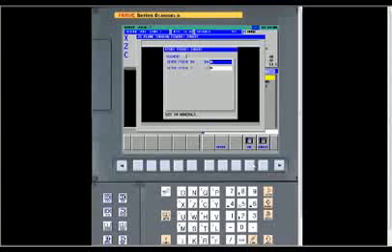You don't have to allow for out in front of the part, because that's within the cycle where we told it to start 100 thousandths away. So it's important when you do this geometry, the trouble most people have is they try to give it too much information.